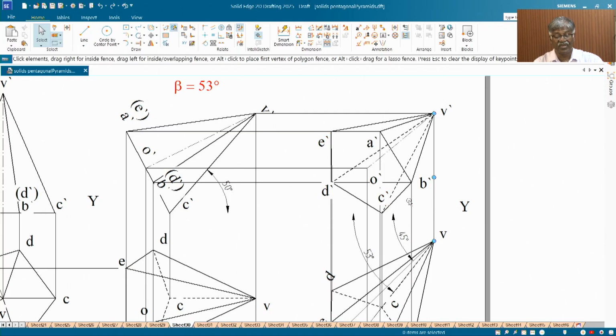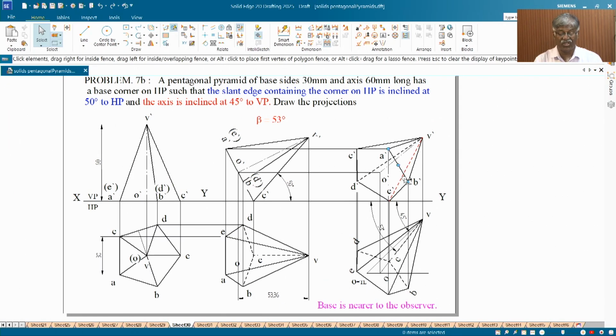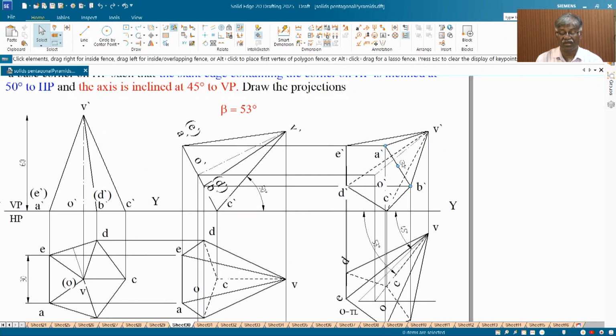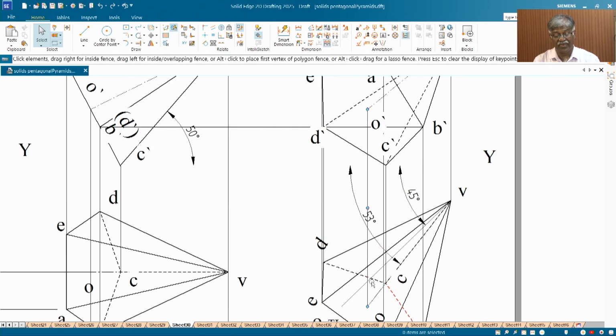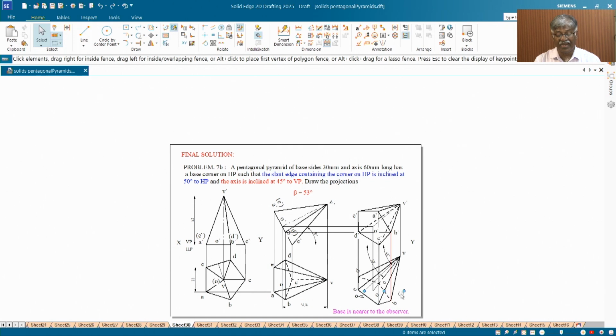See, the visible key surface, the base, is dark. Then the boundary line is completely dark. Then this is a visible bend. These are crossing lines of visible surface and invisible lines. Okay, you can use this for validation. Suppose you do it in one method and check that all crossing lines are opposite in nature, and two lines are already dark, one more line joining that particular corner is also dark, that is a visible bend, or this is an invisible bend. You see, these two are not visible, this is also not visible, this is an invisible bend. Like that you can validate and also clarify the doubts.